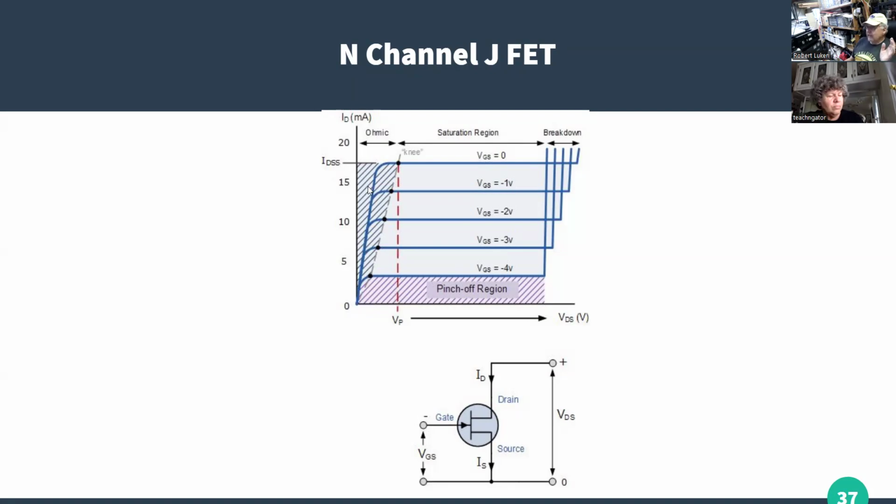If we apply enough voltage on the gate to get it up to the saturation region, it's fully on or conducting. If we operate at gate voltages in the middle, that will determine how much current flows. So we can also use this device not only as a switch, but as an amplifier. Except in this case, the output is proportional to the voltage on the gate, where in the bipolar, the output was proportional to the current going through the gate, of the base.